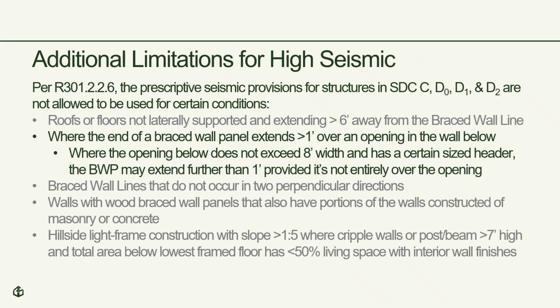The second additional limitation I want to discuss is where the end of a brace wall panel extends greater than 1 foot over an opening in the wall below. Where the opening below does not exceed 8 feet in width and has a certain size header, the brace wall panel may extend further than 1 foot, provided it's not entirely over that opening below.